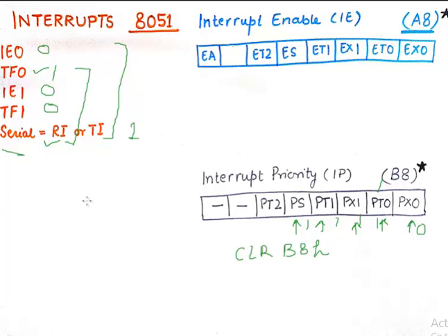And the bit addresses of these registers, by the way, can also be written as IP.0, IP.1. So if you run CLR IP.0, or SETB IP.1, it is equivalent to using their hexadecimal addresses. Having said that, these two special function registers IE and IP are going to control 8051's interrupts.